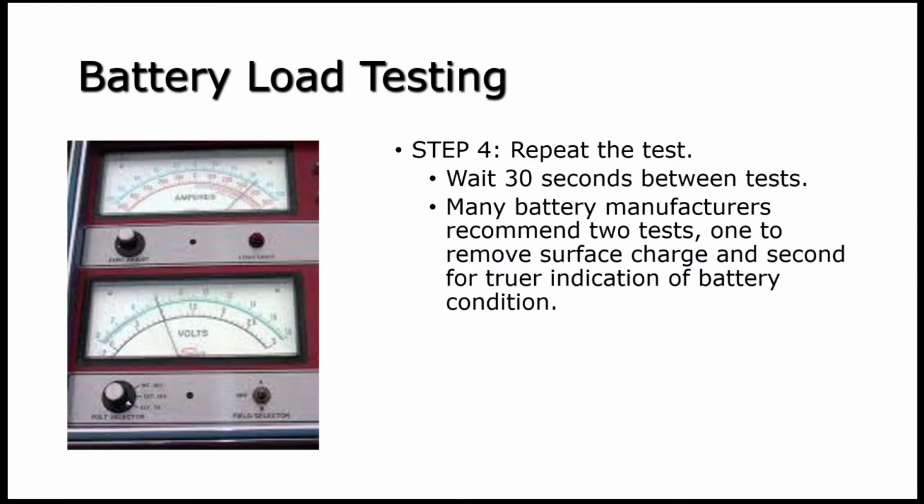And when you do that, the other thing you need to do is make sure that all the lights are off in the car. Make sure no loads are on in the car if you're going to use a capacitance tester of any kind. Everything has to be turned off. So in some cases, it's almost better to just disconnect the negative battery cable, let it sit for 10 minutes, hit it with the capacitance tester, test it, and then hook the car back up. But if you do that on today's cars, that may be a bad thing because you may lose radio settings, presets, all that stuff. So you need to make sure you have a power supply of some sort to supply power back to all those devices, okay? And we'll talk about that in the lecture video and the lab demo video, okay?